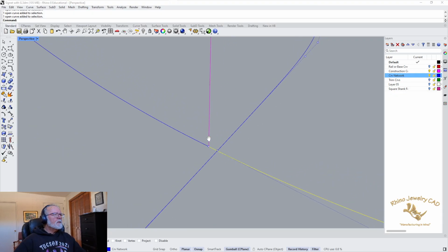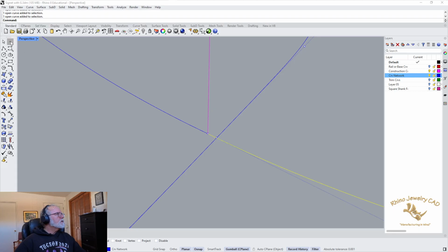But what happens now is that Rhino, let me demonstrate this. I'm going to just put a single point, and I have quad, my dumb face is in the way here, but I have the quad O snap checked, right? And so watch what happens. There's a quad here, and there's another quad here. And what I should have done,